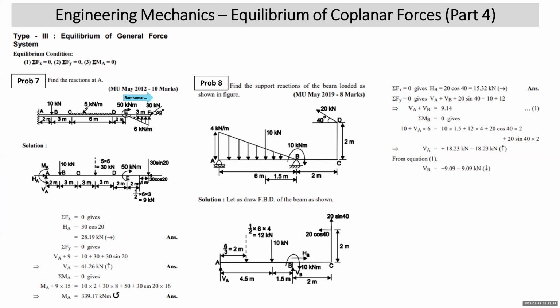अभी और क्या बच गया? अभी ये triangular load बच गया. ये triangular load में arrows are upward, so equivalent point load will be upward. Its intensity is 0 at the left hand and 6 at the right hand. It is acting over a length of 3 meters.